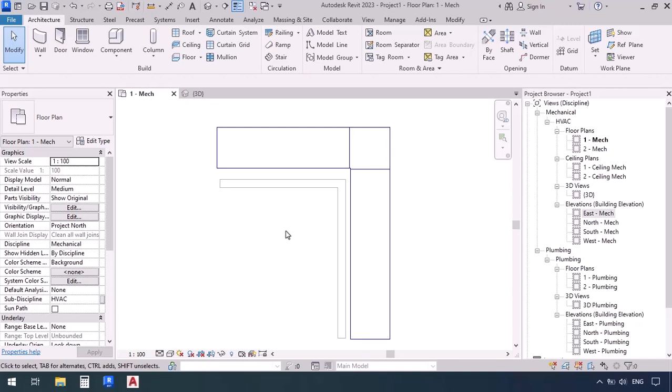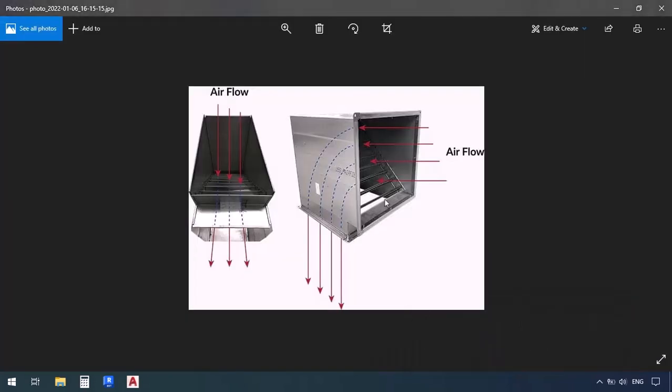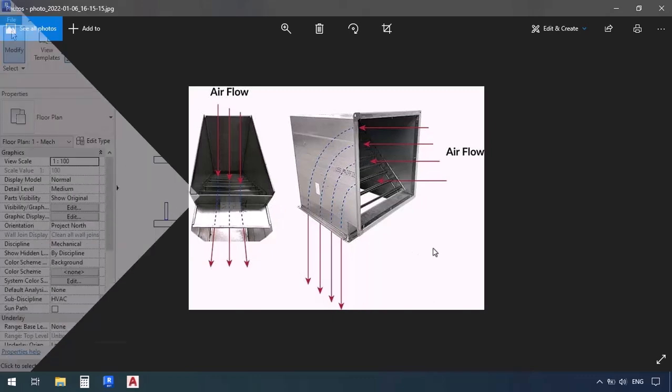But as we've also said before, this elbow lowers the pressure a little bit. And to solve that issue, some vanes can be included in the elbow. They are called turning vanes, which help the air flow a little easier. If you look here in this picture, you can see these little vanes installed into the elbow. And we can see the airflow by these blue dash lines. So this means that the airflow wouldn't get stuck here in these sharp corners. So the air would flow in this direction that you can see.